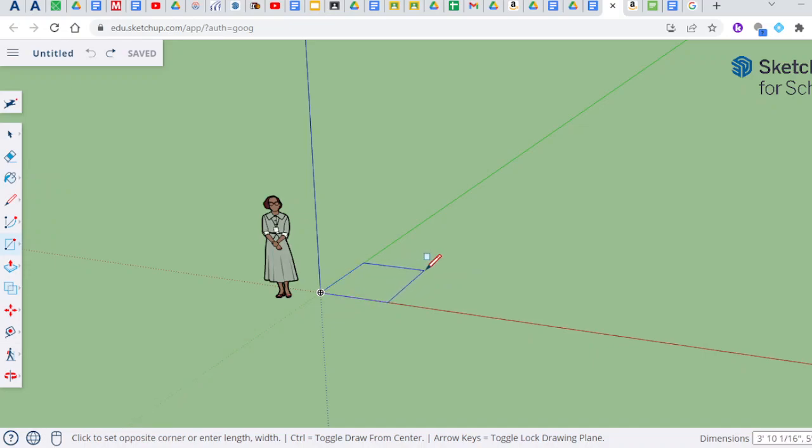Once you know how you're pulling it, you don't click again. You just take your finger off the trackpad. I hit 4 and then my apostrophe, then a comma, another 4, another apostrophe, and then enter. When you do that, you get this lovely shape.